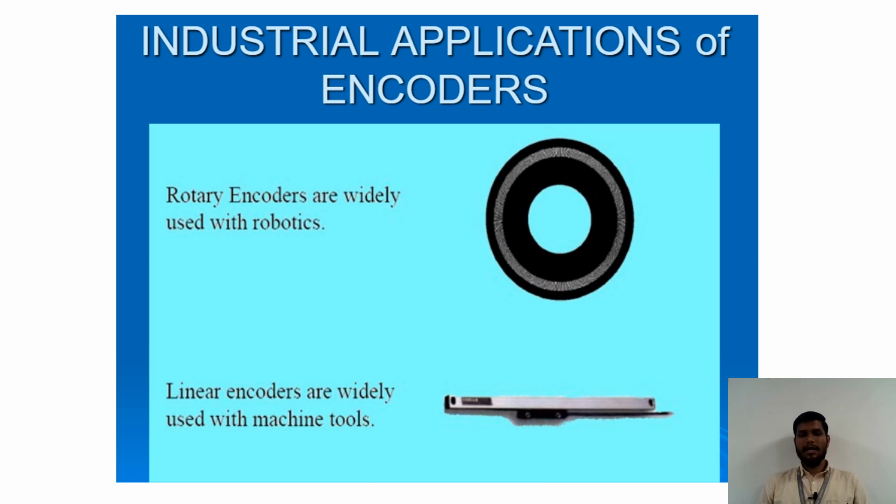The linear encoders are connected partly to the machine structure or guide and partly to the slide which moves over stationary guideways. The principle of operation of a linear incremental encoder is nearly the same as that of the rotary encoder. Here, instead of discs, glass scales with line grating are used, which have line graduations. The relative movement between the glass scale fixed to the slide and the photoelectric sensing device fixed to the guide results in alternate light pulses which generate electric pulses. The periodic signals are processed and converted into equivalent linear movements.